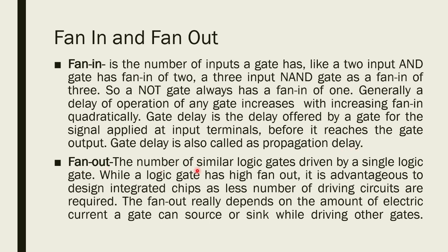Fan out is the number of similar logic gates driven by a single logic gate. While a logic gate has high fan in, it is advantageous to design integrated chips as fewer driving circuits are required. The fan out depends on the amount of electric current a gate can source or sink while driving other gates. So, when a logic gate output is loaded beyond its rated fan out, the particular logic gate has certain effects.